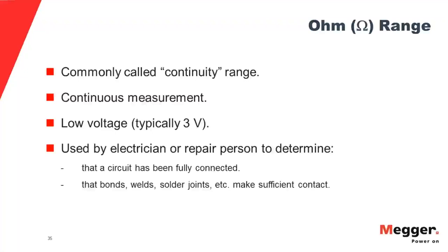So on a continuity test, you test your circuit, and you want to see an ohm or something like that. And if there's a problem anywhere on the circuit, you get a higher number, and you know that there's an issue that has to be corrected.